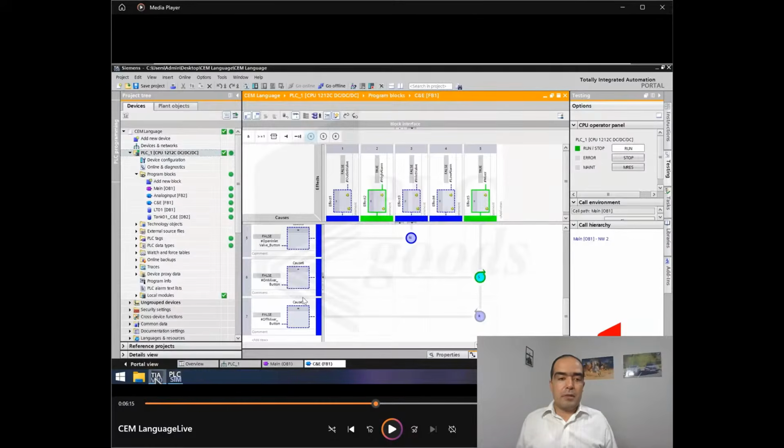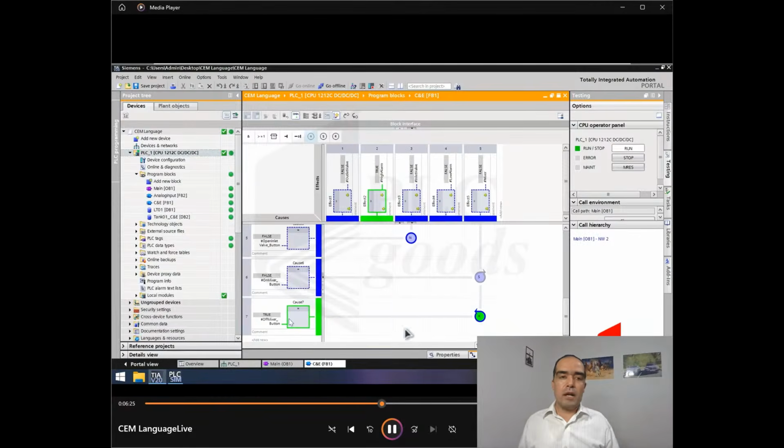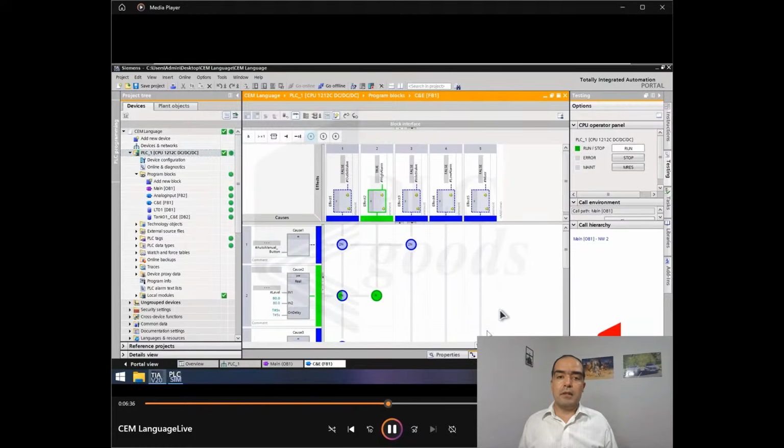As you saw, based on cause number 6, the fifth effect is activated, and this output mixer is enabled. Now let's press the off mixer button. As you saw, now based on cause number 7, the last effect is disabled because I use a reset action for my last cause, which is number 7.